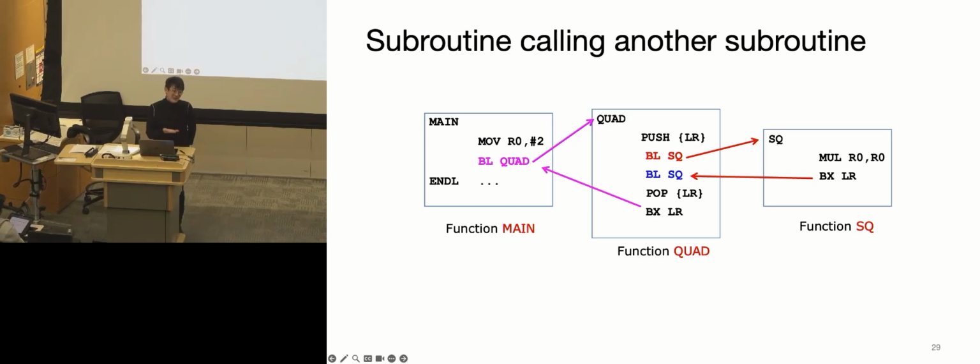Technically, you can do anything. It might result in some undefined behaviors within the program. But for the link register, you should only pop it if it was pushed at some point, and make sure you pop them in the correct order, so that every time it knows where to return to after the subroutine call ends.